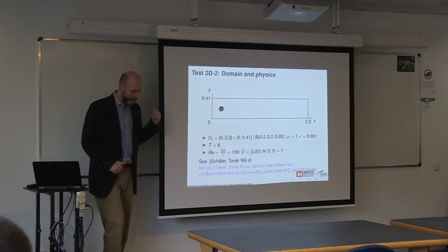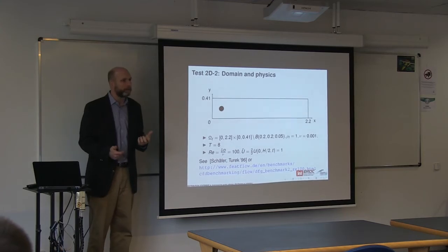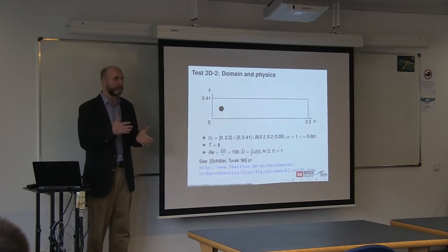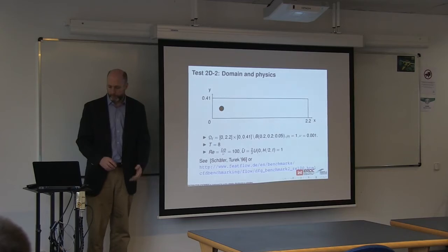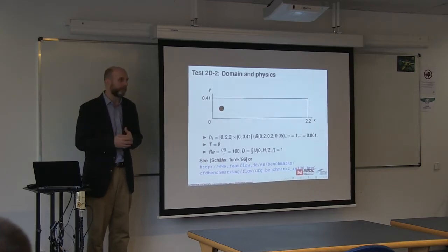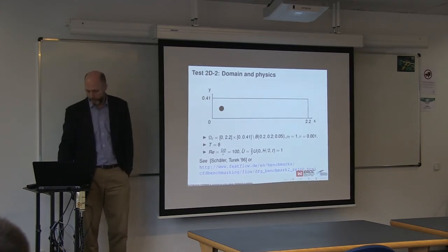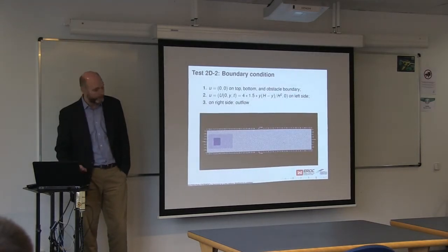However, when we were looking at these problems, we started to see a lot of noise in the calculation of the drag and the lift, and so we went back to some of the standard CFD test problems for simple geometry. So there's Schaefer and Turek, of course, who developed these a long time ago now, so those are nice benchmarks that are well known. And so we went back and recalculated those with the immersed boundary method.